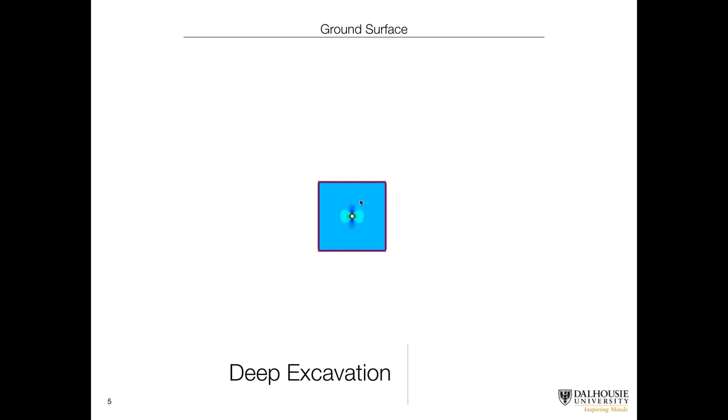So, when we're deep down underground, say several hundred meters, and we're looking at a fairly small excavation here, this one is about 4 meters in diameter, the gravitational component is quite negligible relative to the overall stresses at this depth.